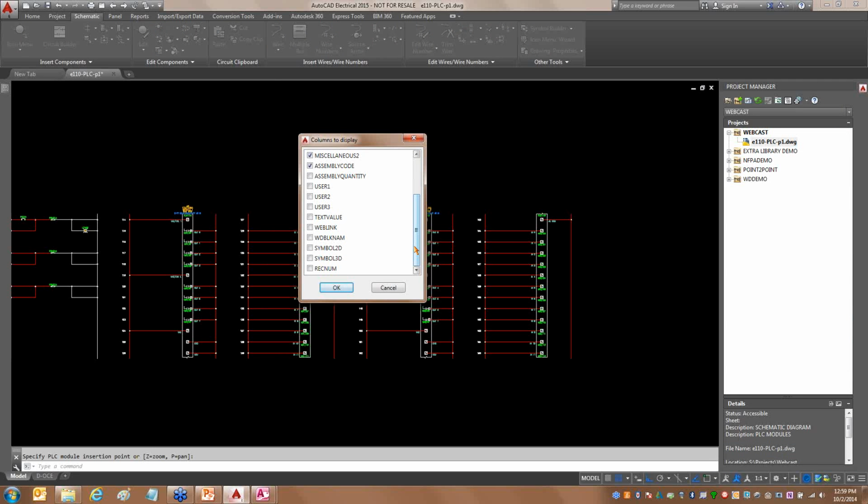Very good. Now one thing I'll point out here, if you'll notice when I was editing after Symbol 2D and 3D, we had coil pins and pin lists, and they don't show up in here. They're in a different table, and when you edit, it's looking at both tables at the same time. When you're searching the catalog database, it's not going to show columns that are in other tables, and there's a couple of these that are in other tables that won't show up that you'll see in edit. But these are all the ones that are in the PB table of the default catalog, or the LT table of the default catalog. Anything else?